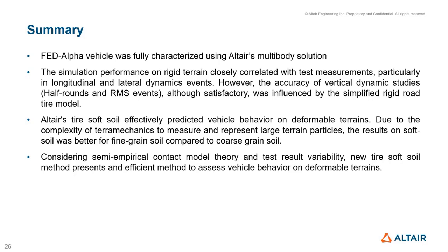So considering this semi-empirical contact model and the test result variability, this new tire soft soil method presents a very efficient way to assess the vehicle behavior on deformable terrains. Also because the simulation runs very fast compared to other solutions like the discrete element method. And the outcome of it is very close to what is required. So if the user needs to perform design studies or validation of the vehicle performance on these terrains in a quick manner, this soft soil model is suitable for these applications.